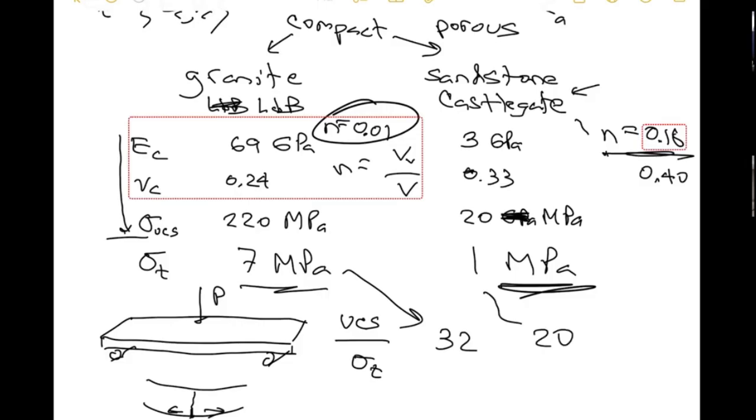Now, remember I said in the world of rock mechanics, you pretty much always measure that. Usually, if we're doing anything serious, something that you're going to build, you do those Brazilian tests. And they're quite easy to do because you just need 2 steel platens, which you already have for the UCS test. You just take some specimens and turn them on their side, and you get Brazilian strength.